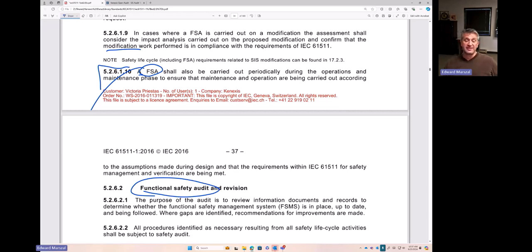And I've already told you that the answer is that an FSA is an audit on the work you did for a specific project, whereas the functional safety audit is more of a mechanism for compliance with that OSHA PSM rule that says you need to audit every 3 years in the US all of your process safety management programs, and functional safety is a small subset, one of those programs that fall under that once every 3 year audit regime.